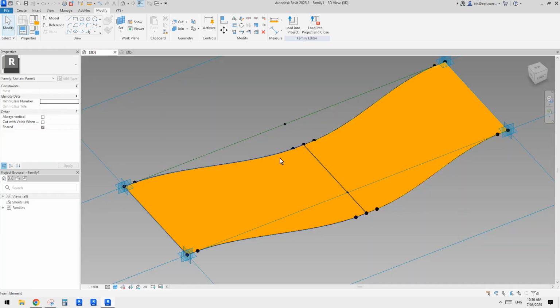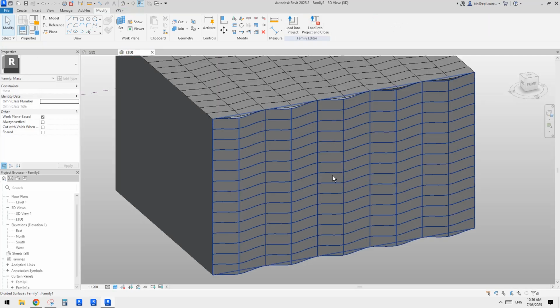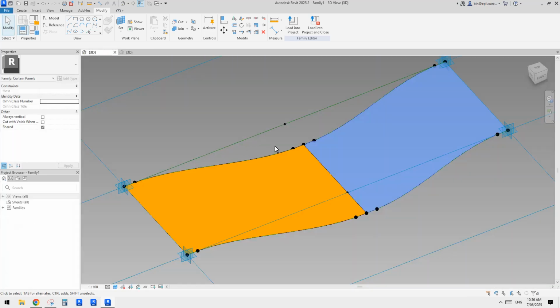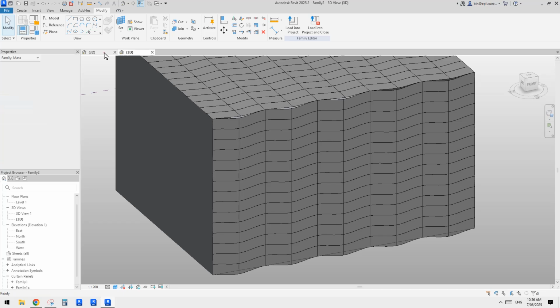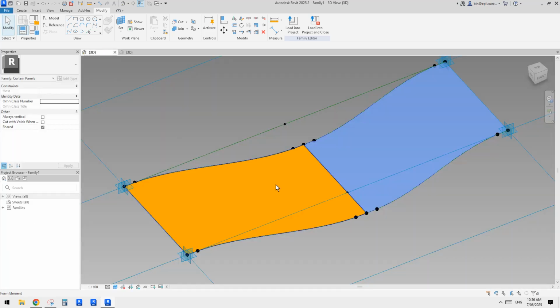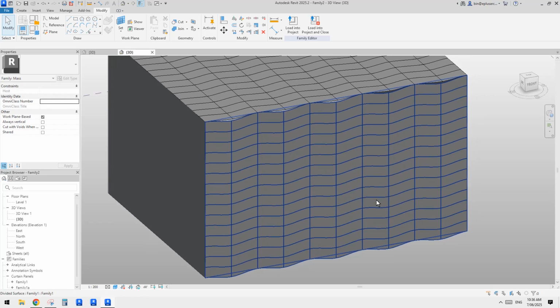the color of the default material in this family and load it back into here, it's just like when we load a family into a project: the material in the project will overwrite the material in the family. Unless the material in the family does not exist in the project, and then we'll just bring in the material with all the settings. But if there's already a material with the same name in the project, or in this case, in this conceptual mass, it won't override, it won't change the color.